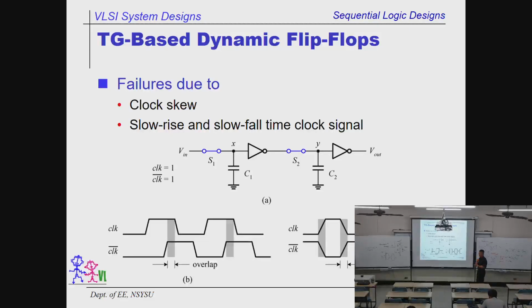Because those machines are coupled with a lot of noise, and the power supply is given by the power outlet on the wall. It's not stable at all. So this is the reason why I always ask them, if you want to do that, that's fine. Please generate all the clocks internally, and you got to add another testing circuit to make sure that all the clocks are generated correctly.